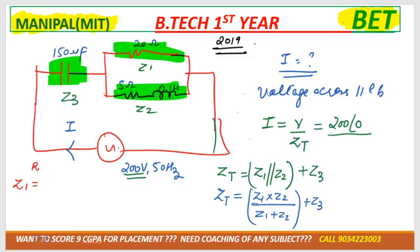If I write it in rectangular form, that is R plus JX. So in this, only resistance is given, no inductance, no capacitance, so we can consider only 20 plus J0. Can I write it like this? Similarly, Z2. Z2 is in the form of R plus JXL.